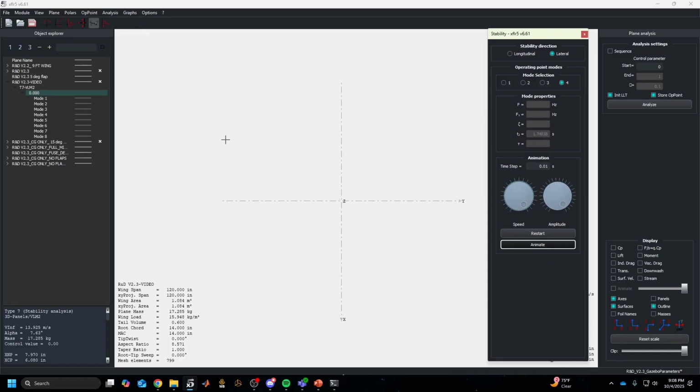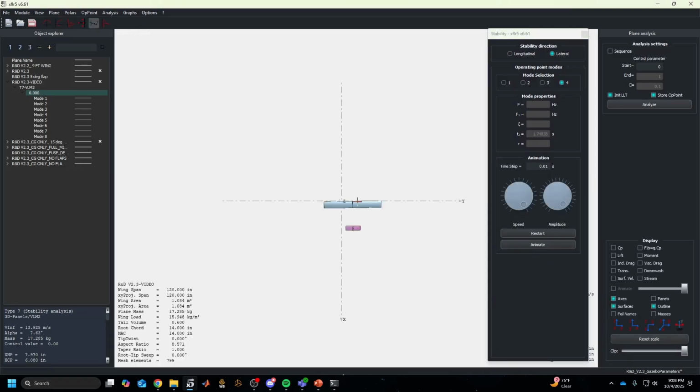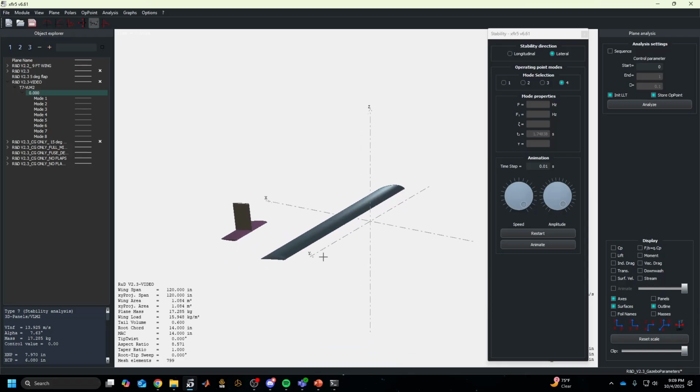We'll do that. So that was a description of our dynamic stability. So after you've done your static stability, you need to show that your plane is statically stable. And then you should show that it is also dynamically stable, okay, by doing your masses. If you don't have masses at the time that you're doing this, static is fine until we get masses. But, you know, use your resources to weigh your wing, right, whether that's through your CAD or actual weighing.